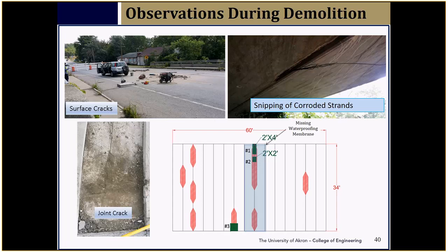Right. So they're going to run the equipment across. It's hard enough to put the rollers on one side, the paver on the other, fill the paver up, and then bring the paver out across the deck before you put any equipment on the deck. I've seen it done that way, but that's a smart contractor. One thing that might help is to inspect the membrane before they actually do the asphalt cut. Again, we make these changes, we change it.